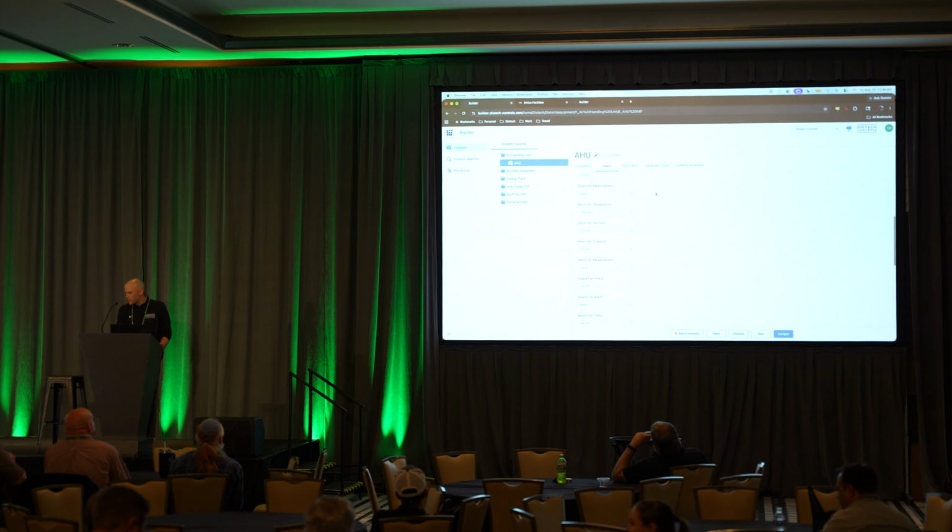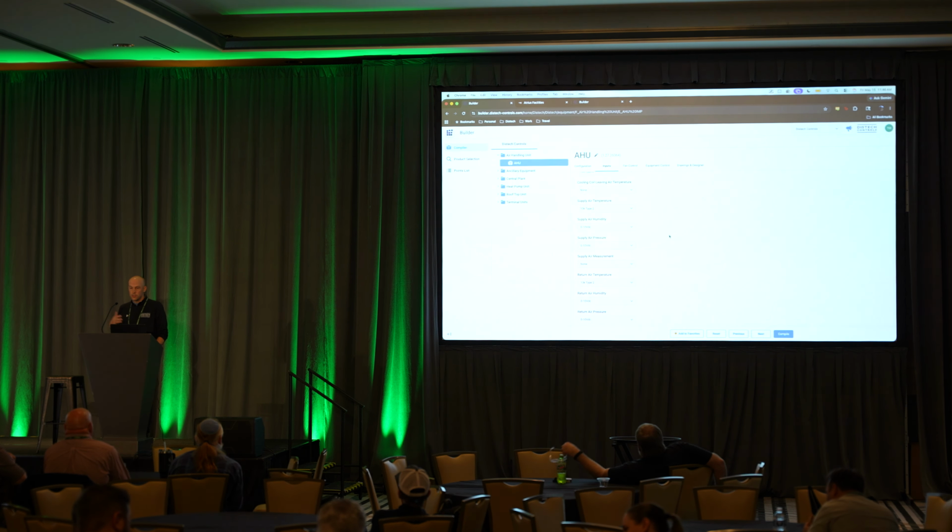One of the things that we do really well is, let me see if I can find one. We have options for auxiliary contacts, but there's also a spot in here, maybe not in the air handler application, where we can actually share data across multiple controllers. So it says network value or analog value, like a BACnet object. If you're sharing data across controllers, we do a really good job of getting all of those use cases in here. So that's a good indication in the dropdown for inputs as well. If you see that, that's software instead of physical hardware.